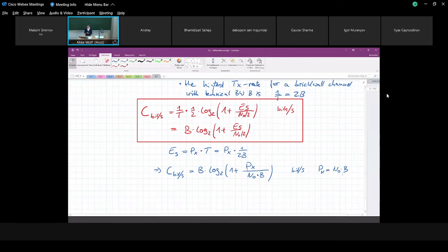But we can even take a look at a different thing, and this is the well-known required energy per bit level, energy per bit to noise power ratio. Now let's say this is basically the highest bit rate which is possible at an arbitrarily low error rate, right? This capacity, bit per second, yeah? Let's write this here, highest error-free or near error-free message bit rate. If we talk about bit rate, it's always the message bit rate.